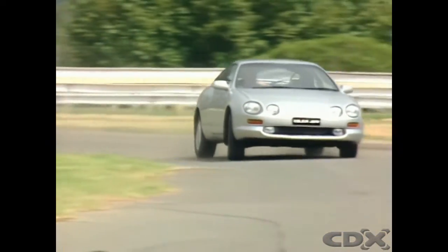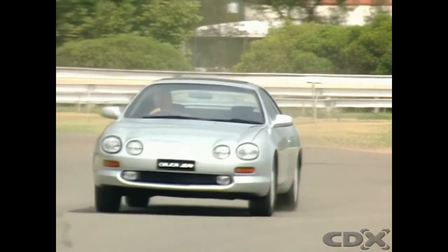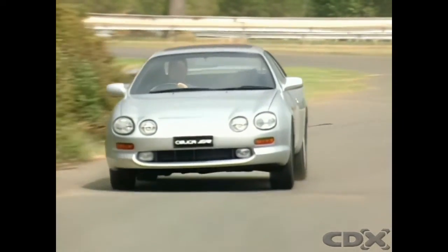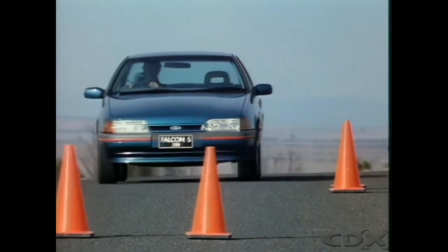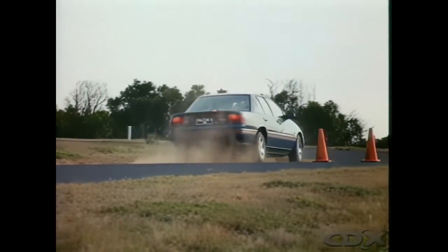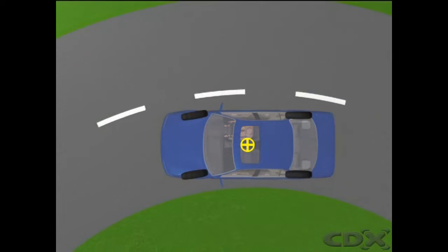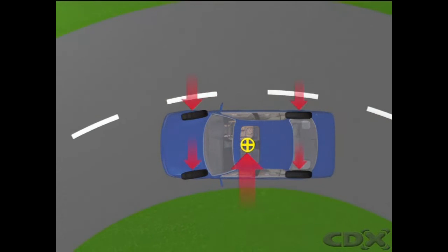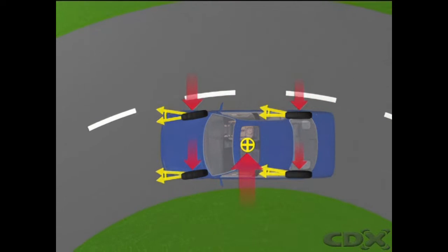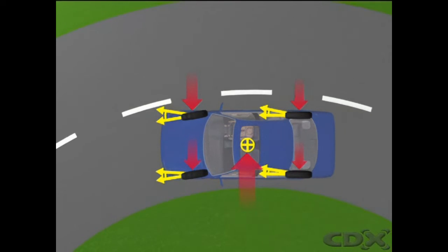During cornering, centrifugal force puts more weight on the outside wheels. Acceleration puts more weight on the rear wheels. Deceleration or braking has the opposite effect. In a turn, centrifugal force tries to push the vehicle away from the corner. This is resisted by the cornering force of the tires. The tires have slip angles due to the cornering forces acting on them. And since the cornering forces at front and rear may not be equal, the slip angles at front and rear can be different too.